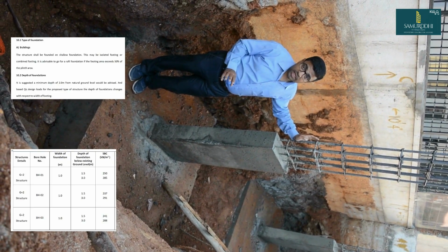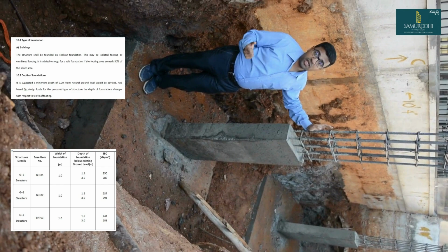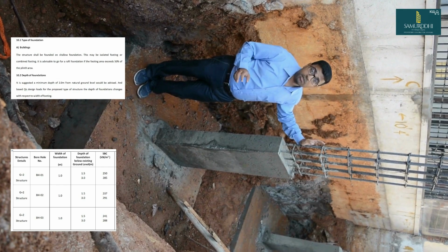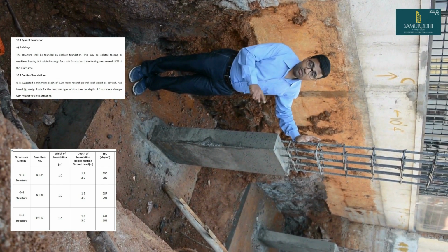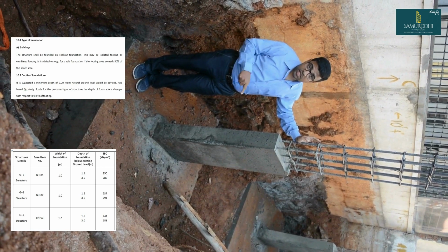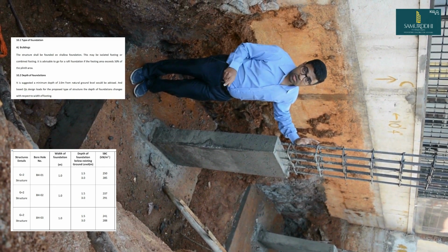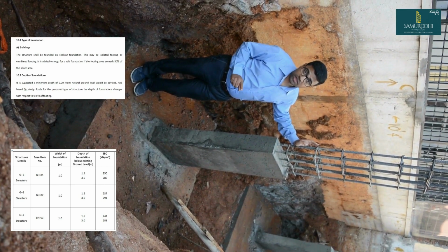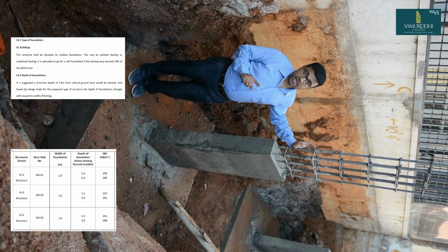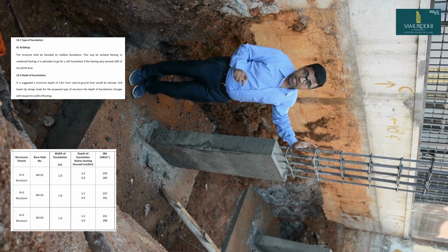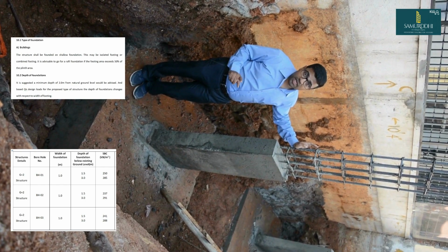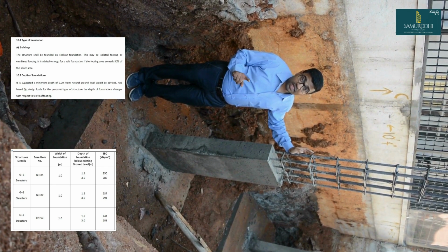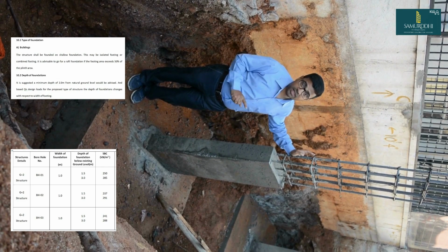So what parameters is the structure design going to rely on? It is the soil test. Soil test for each project is so compulsory, because the type of soil that is there in your site and the capacity of the soil to take the load will decide how much steel and how much concrete needs to be consumed for the designed floor plan to take the load so that it can sustain for a long time, which always differs between projects.